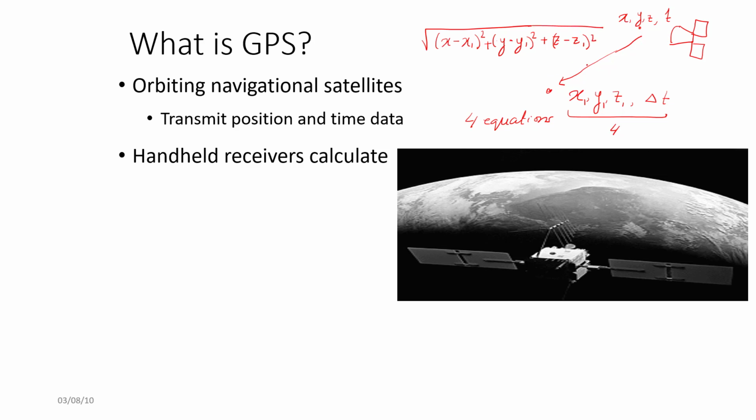Since signals travel at the speed of light, of course here also, depending upon the refractive index of air and so on, corrections have to be made. So let's assume we know the speed of propagation of the signal and let it be c, right? And so then we can find out the time. So basically we know the time, the local time. So if t minus t1 is the time it took, that should ideally be equal to this distance. But then again, we need to factor in the clock skew.